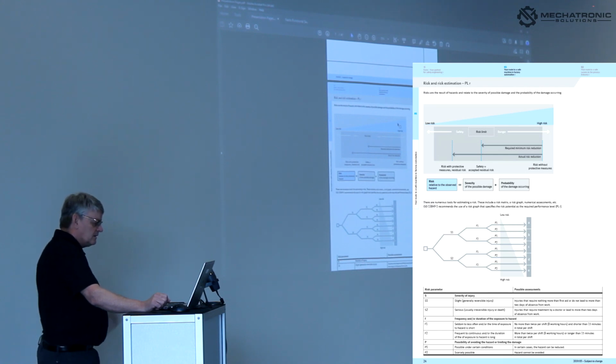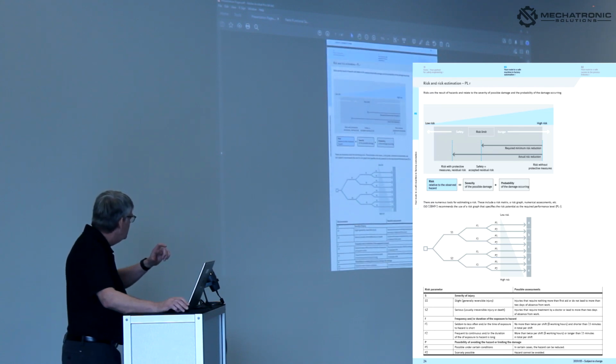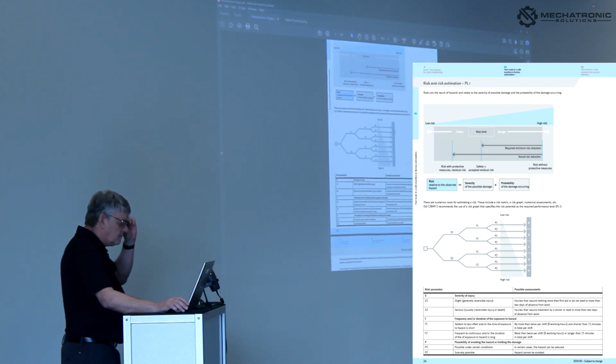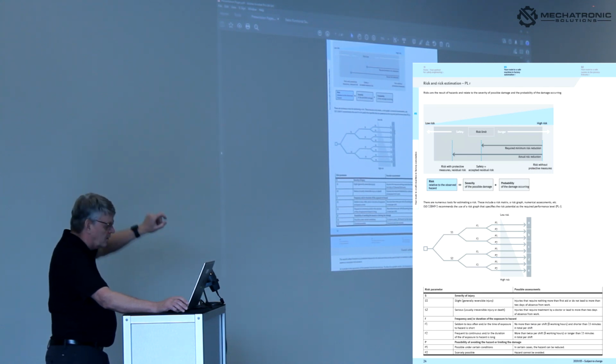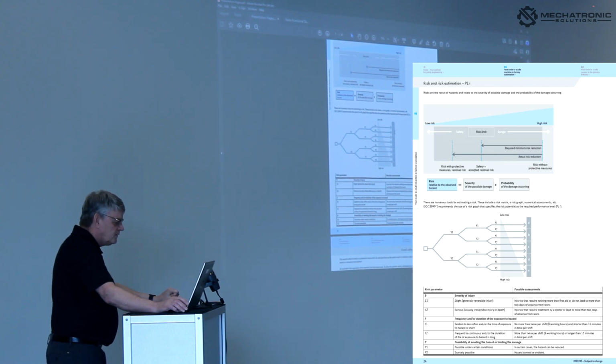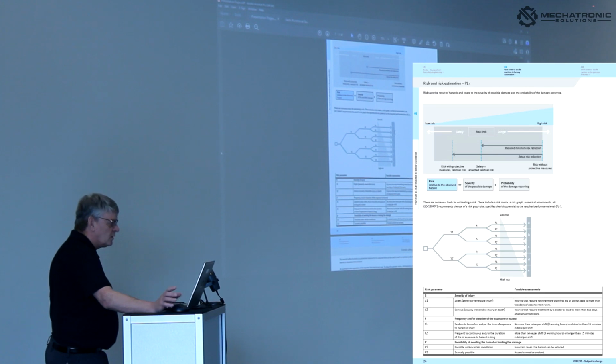The SIL is, you got like 2 channels. You got the S1 and S2. At the very bottom, you can't see it, but you got serious and slight. Slight is S1, serious is S2. That'll pair you into the chart. So you're on the upper rung or the lower rung. And then you've got the frequency. If it's high, low, you go on that rung. And then you've got the possibility of the hazard. You've got P1, P2.